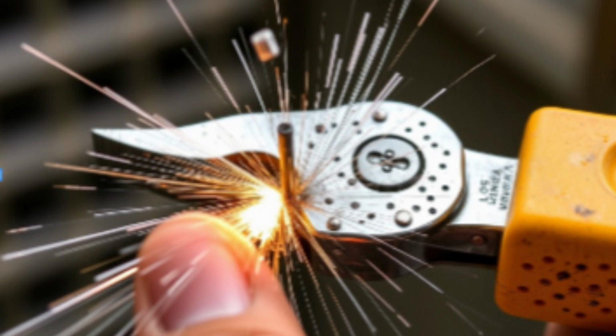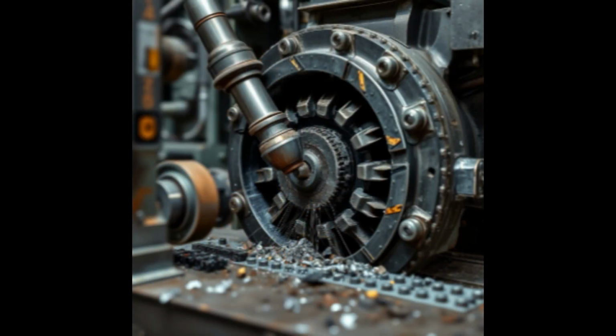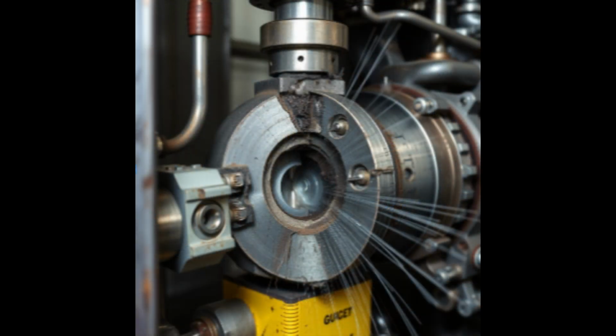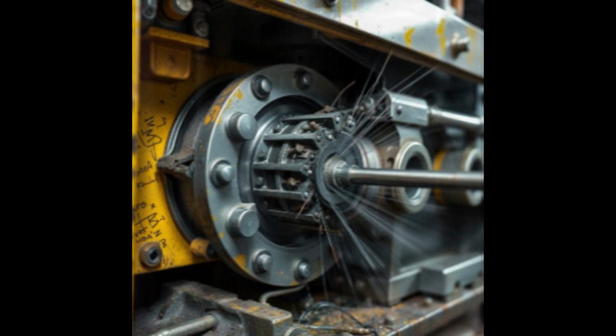Appearance. Impact stress often appears as visible cracks, dents, or fractures in the material, with cracking usually localized around the point of impact. In brittle materials, impact can cause sharp, sudden breaks with jagged edges. In metals and other ductile materials, the impact may leave indentations or signs of bending or deformation near the affected area.